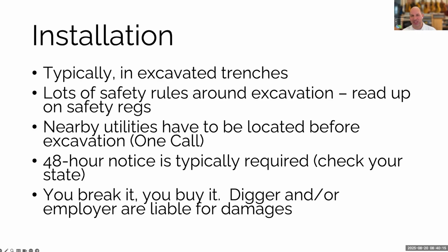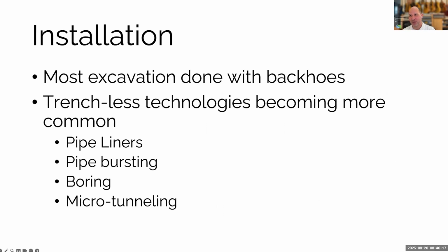Most sewer excavation is really deep, so it's atypical to be sending out crews with shovels, except under small situations where there's not a lot to be dug up. Most excavation is going to be done with backhoes. That being said, those trenchless technologies I talked about, pipe bursting, things like that, pipe lining, horizontal boring, it's becoming more common. I'm not sure how common that is out in the territories right now. Usually excavation is the cheaper option, but sometimes it's just not practical because of existing infrastructure. So they'll go with these other options.